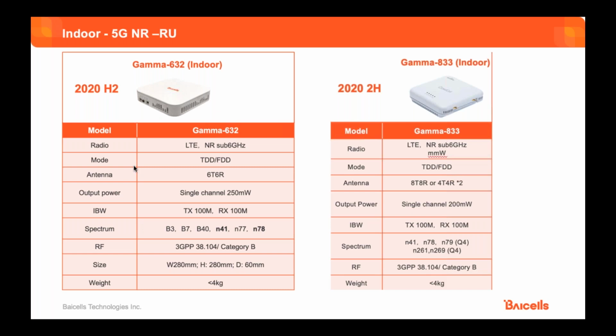5G has, according to the specs, frequency range 1, which is FR1. This is anything below 6 gigahertz. That's why it's called sub 6 gigahertz. And then you have FR2, which is millimeter wave. That's above 28, 30 gigahertz. You will go into what's called millimeter wave.